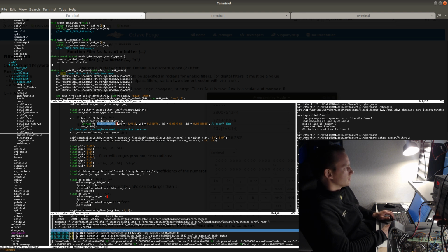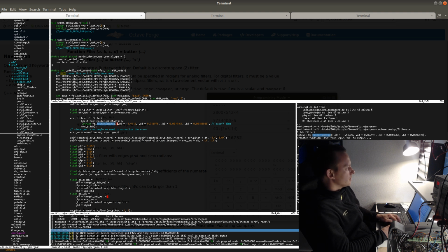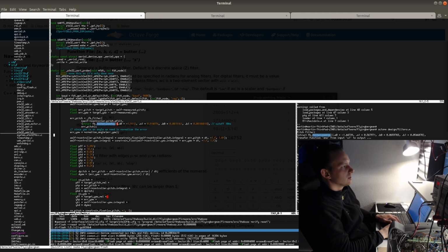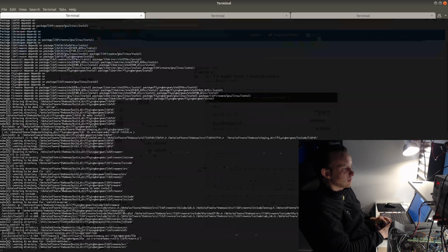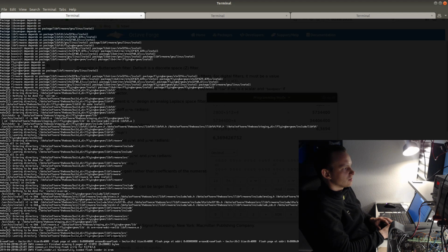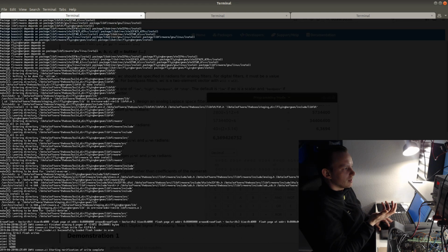First I need to check something that happened in the firmware. Oh, actually, I know what happened. It failed to verify because I have to power off the motors for it to verify. I think this has something to do with ST-Link reception of data. Maybe it's missing some pull-up resistor. So the verification phase actually fails.